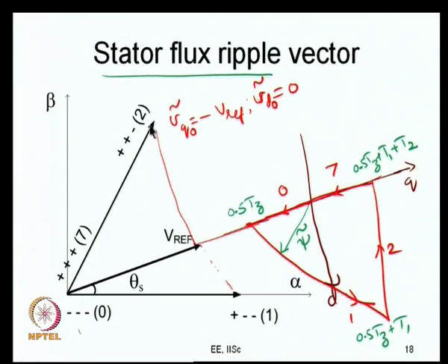Therefore, your applied voltage vector is here, the desired vector is here, and this is your error voltage vector. Now you are integrating the error voltage vector, so the tip of psi tilde vector moves like this and reaches this point at 0.5 Tz plus t1 plus t2, and subsequently when you apply the error voltage vector, it moves back in this direction now.